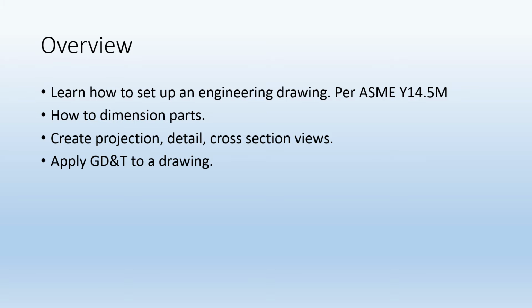So you imagine you have a square aluminum plate, call it 1/2 inch thick, 3 by 3, and you want to make a hole right in the center. So you dimension that hole probably from the sides of the part. So you come in 1.5 inches from the left, 1.5 inches from the bottom, put your drill hole right there. Well, there's one problem. There's really no way to ensure that when they drill that hole, it's going to be exactly to the atom right where you placed it. And because of this, we have tolerancing on drawings.